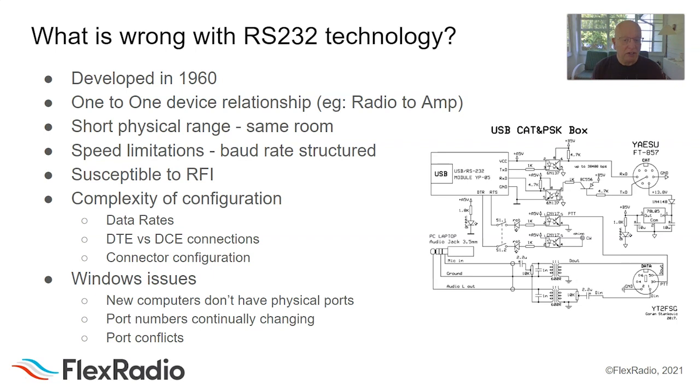It's more wires in your hamshack. Well, that can result in more RFI issues. It can radiate noise, affecting your ability to hear, but also can be RF getting back into the computer, causing keyboard lockups and really strange things. And this is not just related to, I've seen people say, oh, my SWR is great, but I have RFI issues. Well, probably because if your SWR is good and your antenna is good, you're radiating more RF. And if you're radiating more RF, you could be overloading cables in your hamshack, because every cable is actually an antenna.